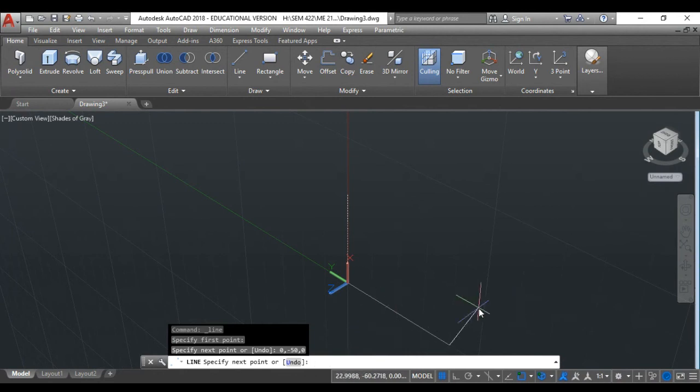Now I'm intending to move up. How far I should go in that direction? Again, think about it this way, x, y, z. Okay, or I can activate what, guys? Remember ortho mode? So from now on, all the lines will be drawn along the x-axis and along the y-axis, also and along the z-axis. Okay, how can I enforce my mouse to move along the z-axis?